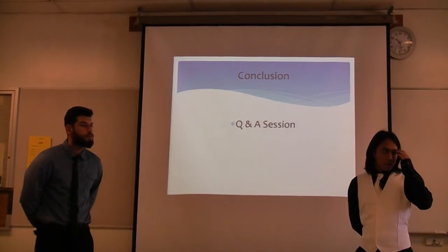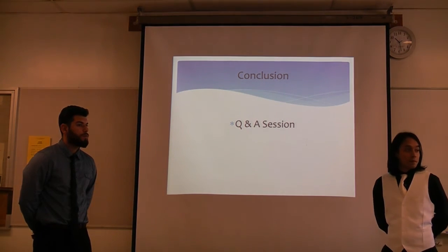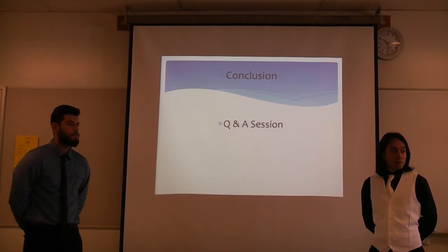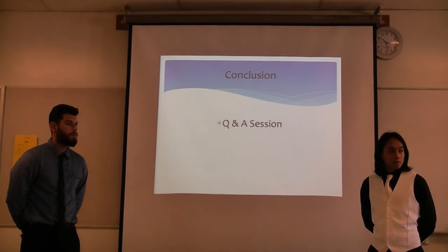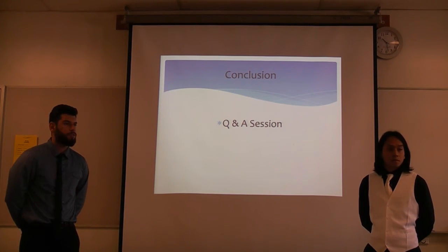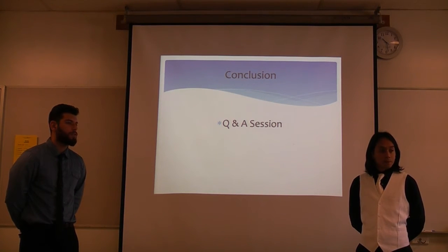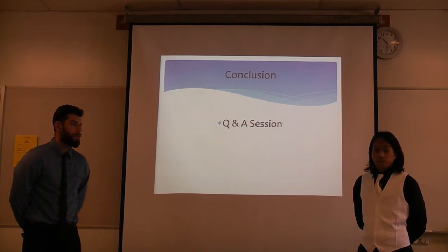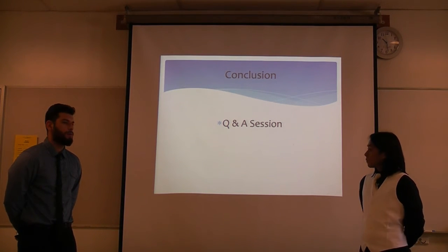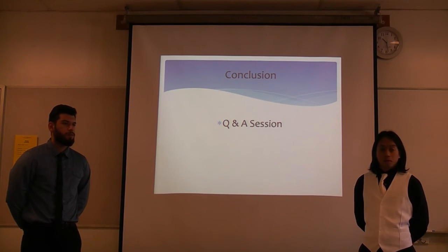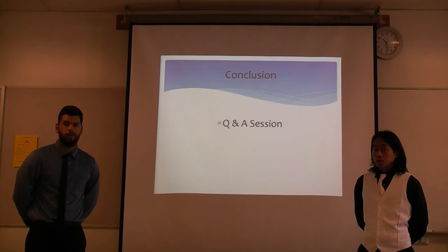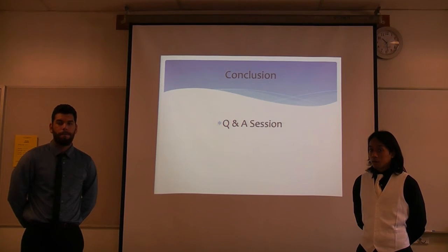On your BIU, you have a series of 2-to-1 muxes. Why did you choose to put 2-to-1 muxes instead of having a bigger mux at the bottom? We wanted to use a more behavioral implementation of the processor. We didn't want to run into any timing issues, so we wanted to keep it simple, even if it meant more control words, as opposed to having a series of 2-to-1s and one big 4 or 5-to-1.